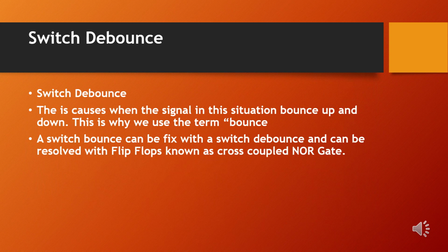Also covered in this lab: switch debounce. This is caused when the signal in this situation bounces up and down. This is why we use the term bounce. A switch bounce can be fixed with a switch debounce and can be resolved with flip-flops known as cross-coupled NOR gates.